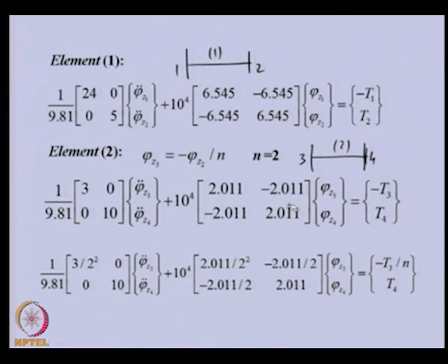Till now we have not used the gear element because now you can see that node 2 and 3 angular displacements are related. So, as such we should eliminate the angular displacement at node 3 in terms of node 2, because we know they are related with the gear ratio like this. If we want to do that, obviously we need to convert this elemental equation according to the geared element which we developed.